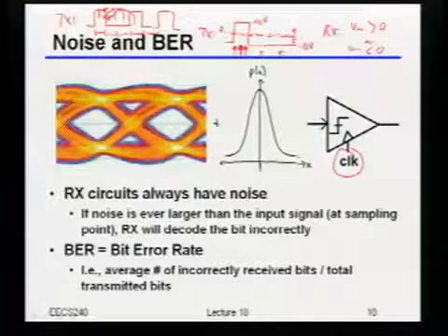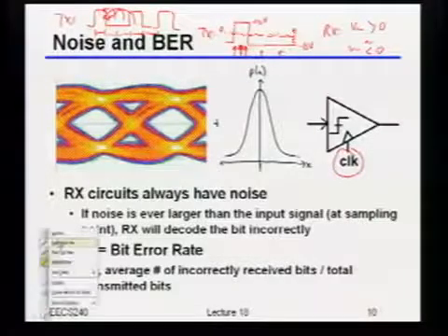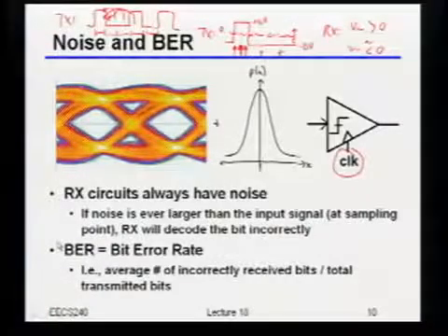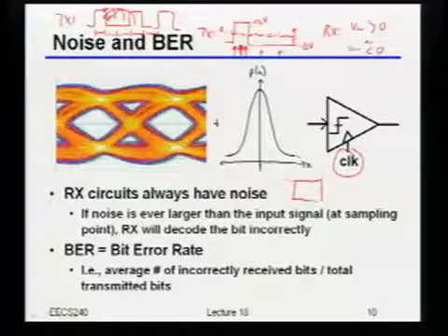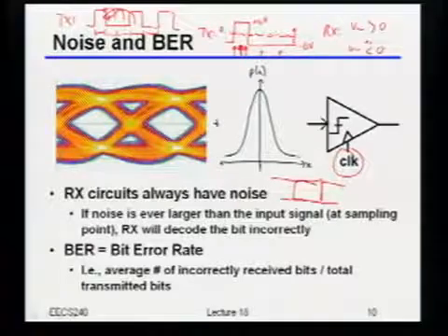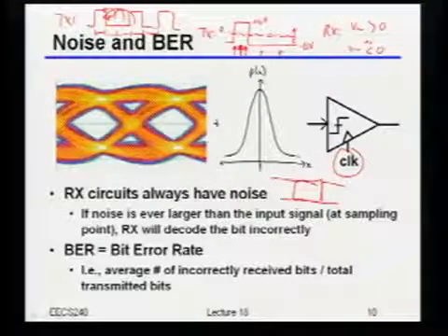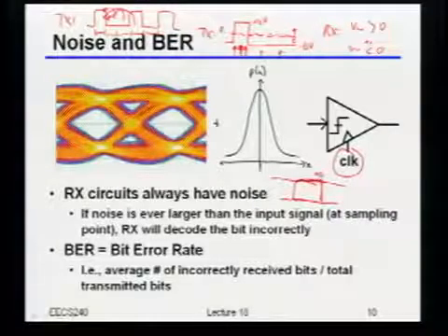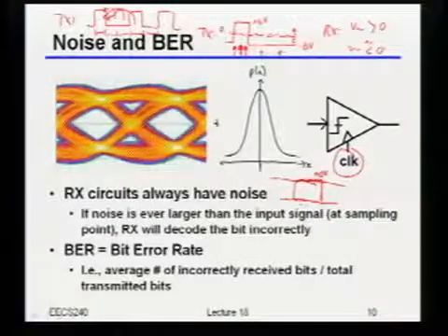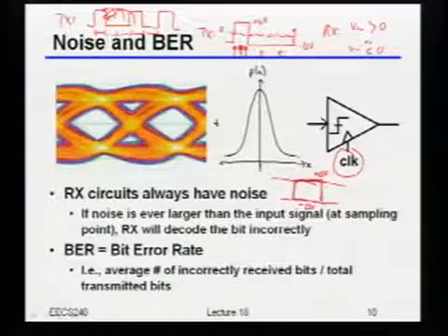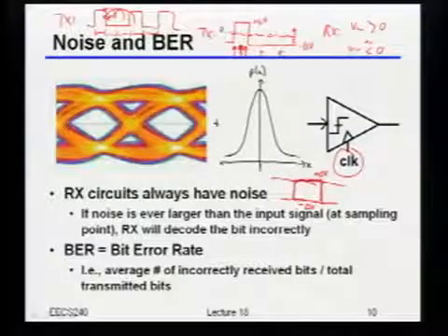The reason this is useful is, imagine I had a perfect transmitter, okay? Then if I looked at that eye diagram, it would basically look something like this, okay? There'd just be this perfect square box there. What this tells you is that I'm always either going to get a perfect plus delta V or perfect minus delta V, and it's always going to transition exactly at these times.